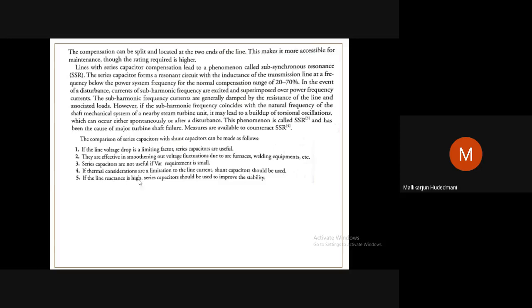If the line reactance XL is very high, shunt compensation at either end will not help you. That is how it should be technically feasible. The line is highly inductive. A series capacitor concept is the only best mechanism, where XL and XC counteracting each other would help the requirement. This way, these are a few points by which we can compare series and parallel compensation for the application.